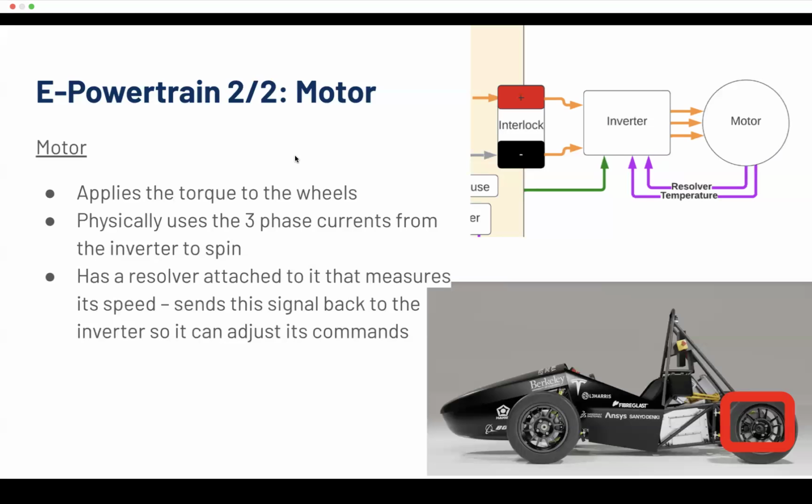But anyway, the way we get ground speed is there are also 4 wheel speed sensors, one on each tire, and that tells you how fast the tires are actually spinning. And then from that, you can calculate your ground speed. Now, there is some oversight there that doesn't account for if your tires slip, which is something you could sense in software from your wheel speed sensor reading if you wanted to do more advanced controls. But we just take the simple wheel speed sensor.